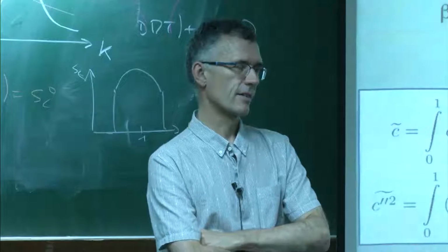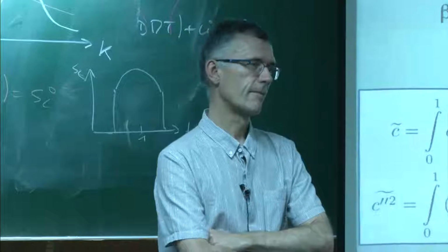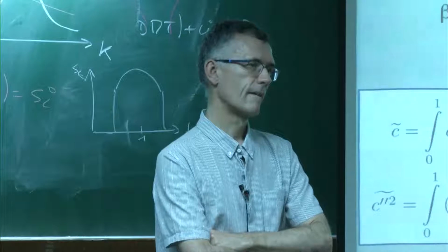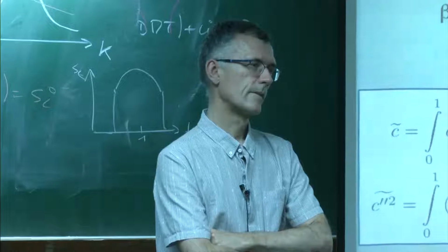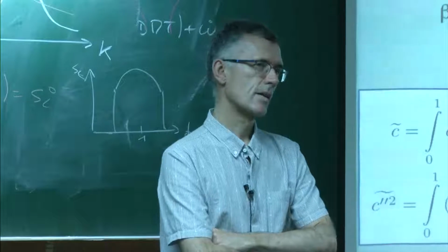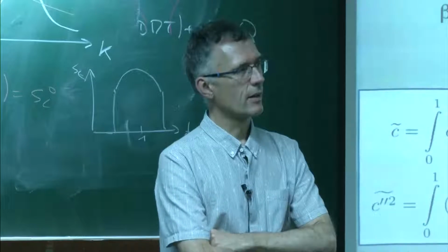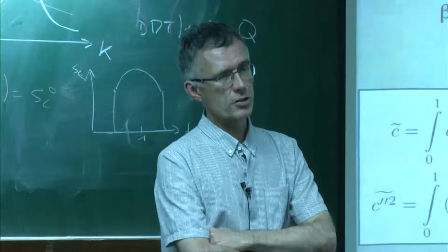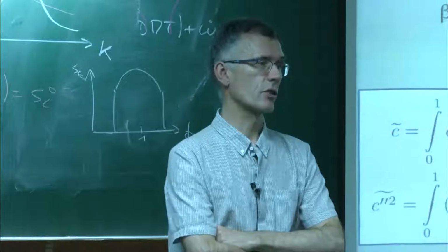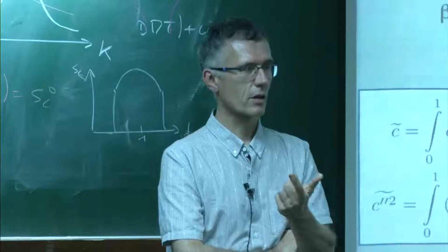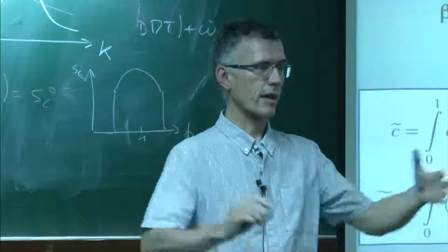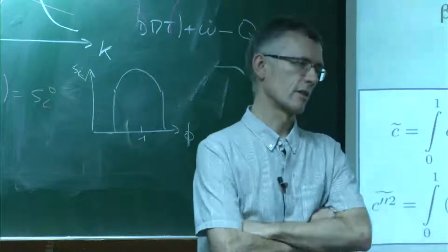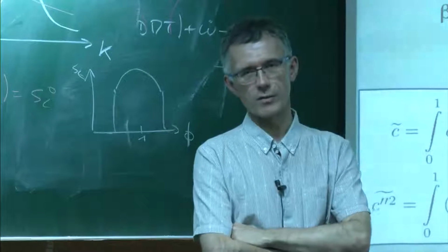One question I had was, do they consider the kinetics in it, or do they have the mixture fraction versus tabulated speed? Well, it depends what you want to do. You're talking about piston engines here. Tabulation in piston engines is really difficult because everything is changing. You have dilution, pressure, equivalence ratio. So the table gets huge, and they're coming back from tabulation at the moment. It's just very complicated.